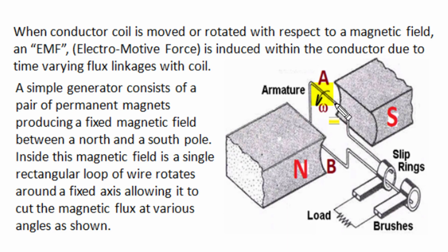When a conductor or a coil is moved or rotated with respect to a magnetic field such that the conductor cuts magnetic lines of force or the coil has time varying flux linkages, then as per Michael Faraday's law of electromagnetic induction, the coil will have dynamically induced EMF or electromotive force.